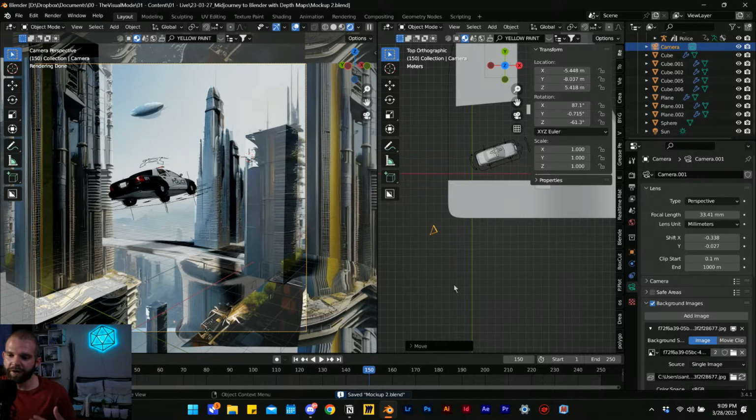In another moment, I will troubleshoot through the Midjourney thing, and when I do bring in Midjourney, because this image was from Blue Willow. Won't give the credit to Blue Willow here. But the next time we bring in Midjourney to create an AI image to bring into Blender, we'll use a depth field or a depth map to basically take an image and convert it into a gradient that informs the 3D surface how it should deform, so that the things that are further away in the image actually create geometries that are further away and then closer up. It's another technique for different purposes.